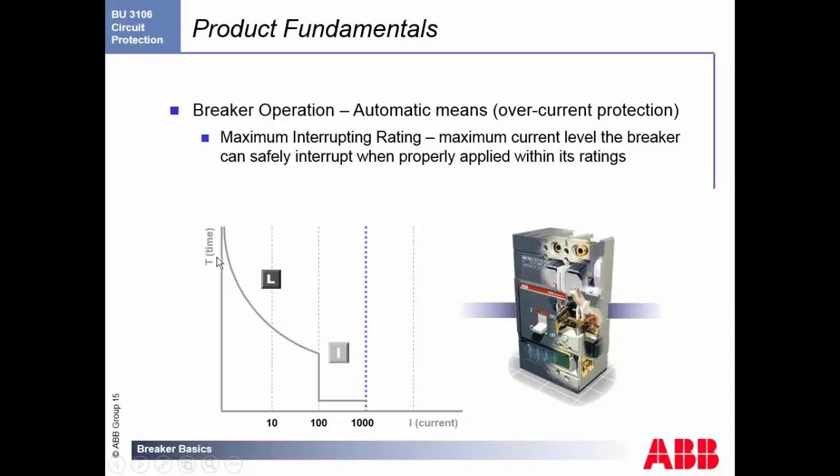So as you can see, it's very important as you are looking at these breakers and speccing out these breakers to know exactly what load and the application you're looking at. Again, if you're looking at a spike, you're going to employ the L, and then you're going to make sure that your time is fine before it levels off, and hopefully your current stays below the instantaneous. Goes above the instantaneous, we're going to open right away, and if you go past even our maximum rating, then we're all in trouble.